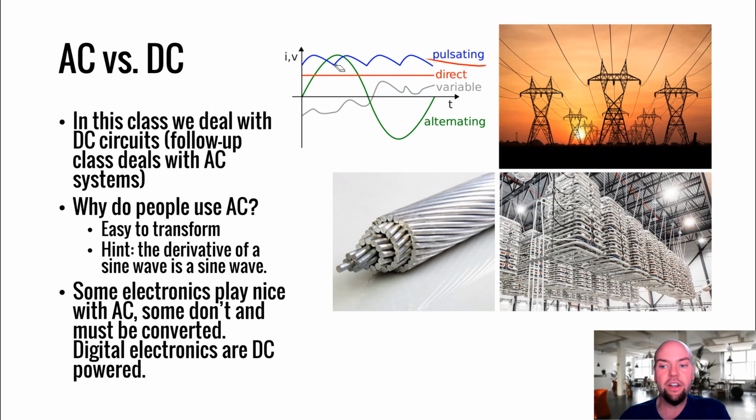And if you transfer a lot of current, you're going to have really fat copper wires that aren't very long, or you're going to lose a lot of power. So the idea is, normally if we want to send power a long distance, the way we do that without spending an enormous amount of money is we convert it to a very high voltage. And we send lots of power as a high voltage with a relatively low current.